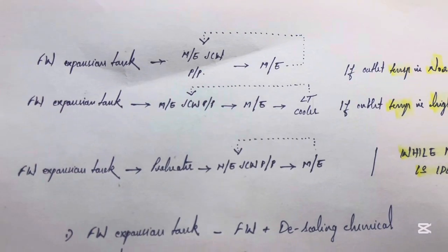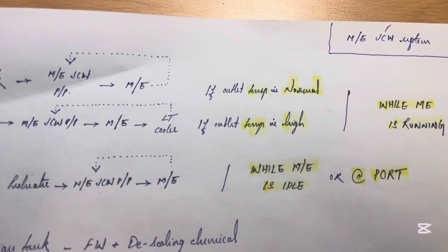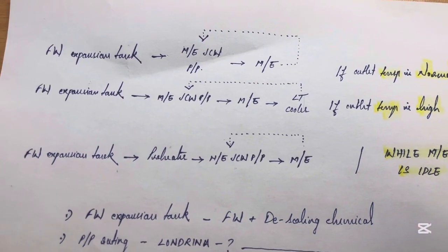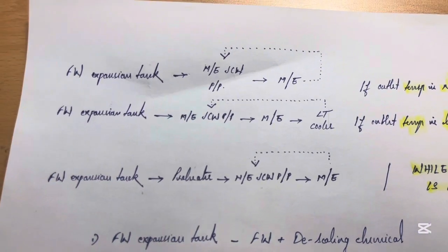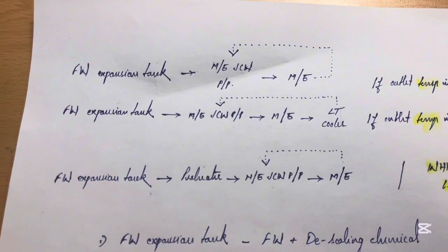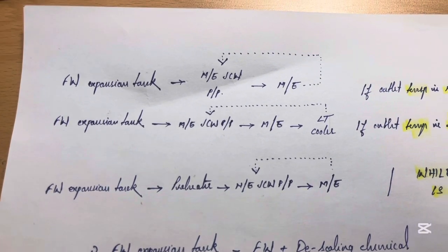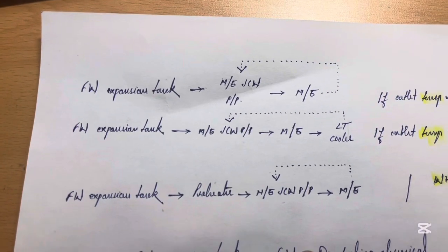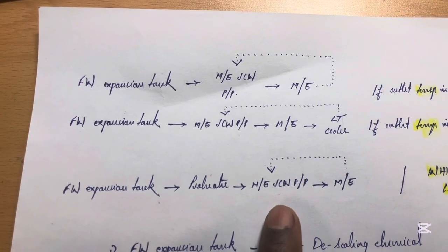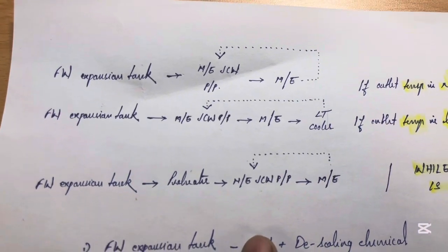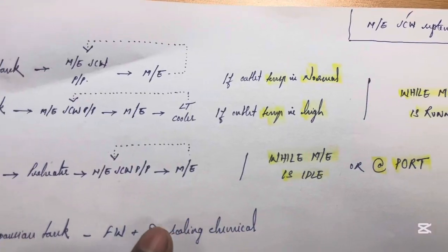Of course the idea is to cool the engine, but you cannot always use cold water. It's like a baby kept in an incubator. The water should also be maintained at a certain temperature, at least ambient temperature. That doesn't mean that if the ambient is cold you have to use cold water. I mean warm water, but not so warm that it adds more heat to the engine, because the main idea is to remove the heat. So this is the thing.